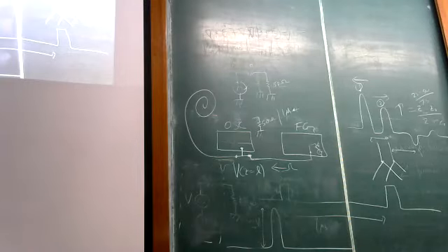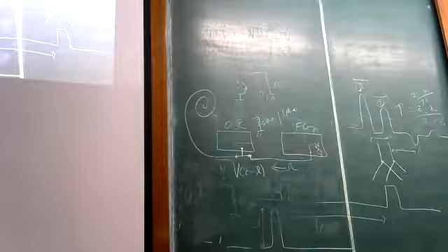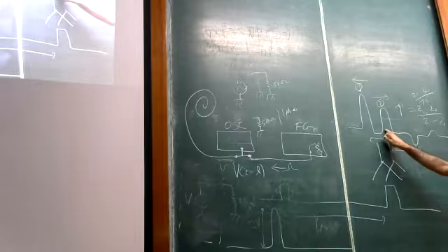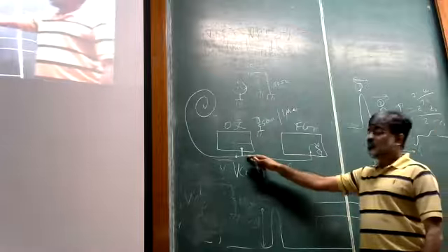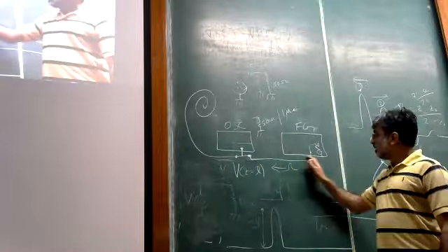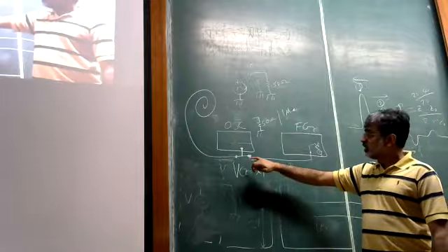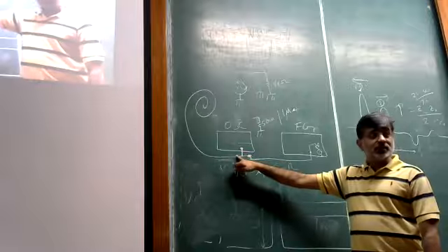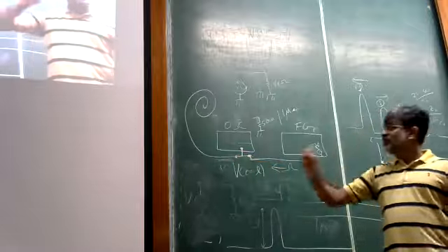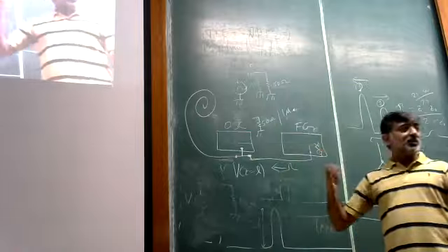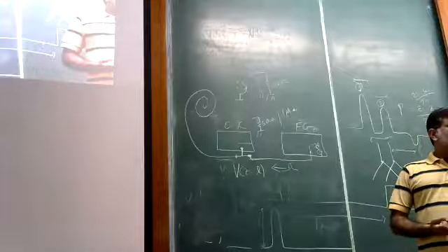So if we could see smaller and smaller pulses, you'll see that this will go on forever. Each time the pulse will have opposite signs, except for the first time. Because at this point, the first wave, when it traveled here, was the first time a pulse came from this direction, and that saw a lower impedance, but the reflected wave went this way, which we didn't care about.